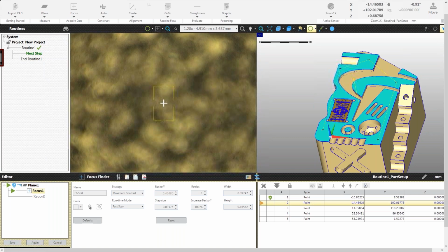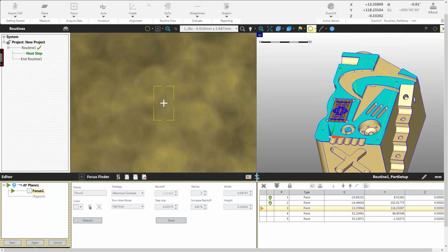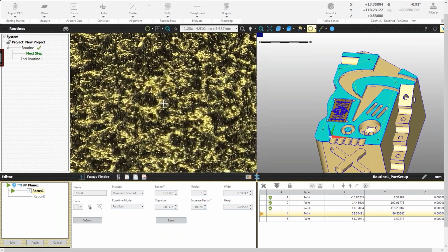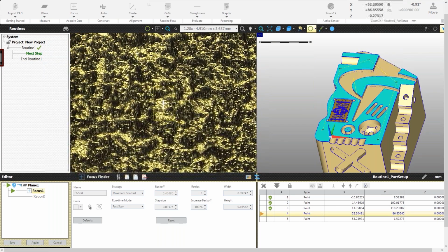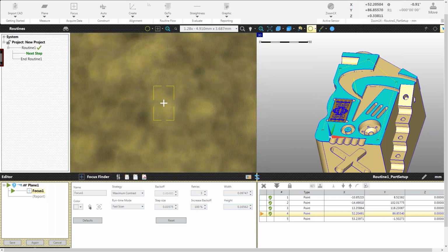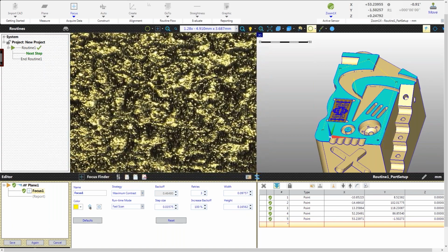What is a plane going to control? Well, it's going to control rotation about the X and Y axes, and it's also going to control translation along the Z axis. It does not control rotation about the Z axis, and does not control translation along the X and Y axis. So dust off your old metrology books and GD&T books and start studying geometry types.